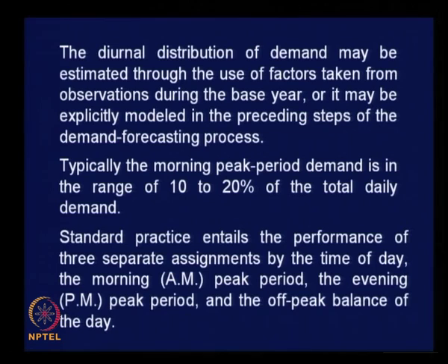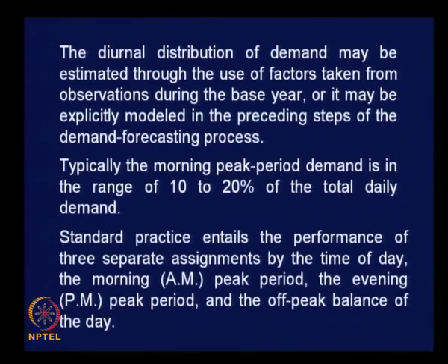You just quantify the demand for AM peak, do the traffic assignment, then PM peak, assign the traffic and visualize the traffic scenario, then non peak period you just quantify the demand and then assign and visualize the traffic flow, right, which is similar to the desired setting for traffic signals.